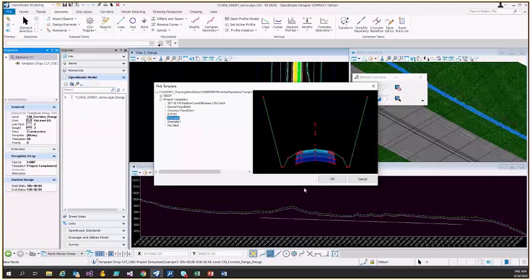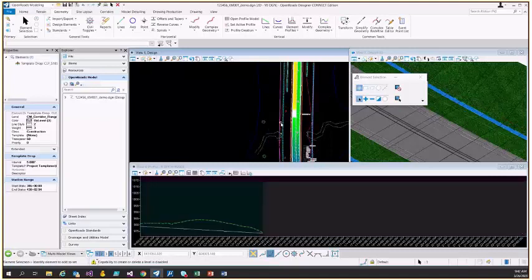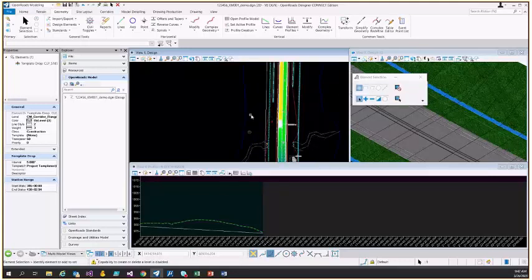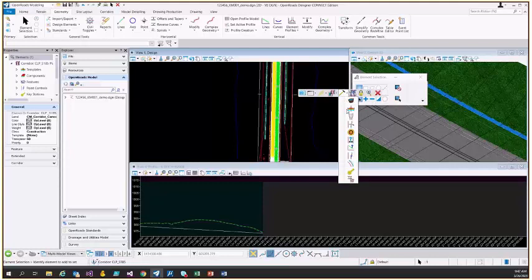So switch that to this one. You'll see the ditch will go away. And now what I'm going to do is add a point control to have this ditch line follow that projected ditch profile that I made. There's obviously a bunch of different ways to kick that off. I'll just click my corridor, come to my corridor creation tools, and add a point control.